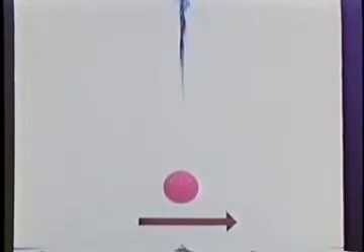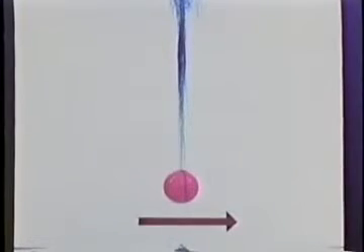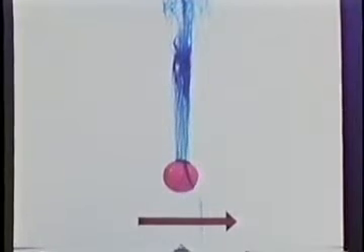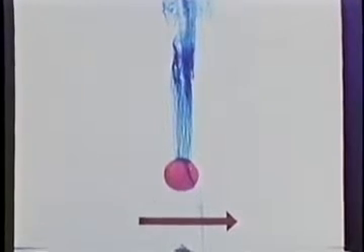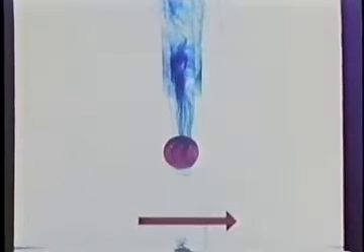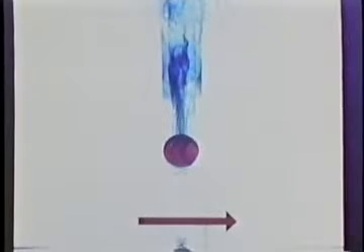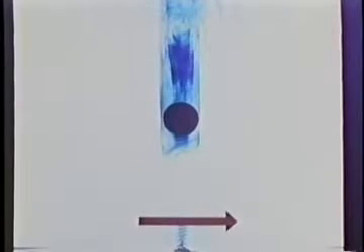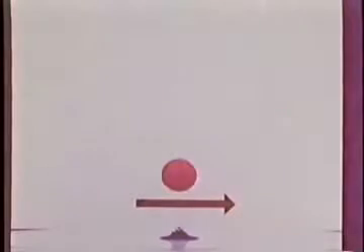Now we have changed our setup so the sphere can be towed vertically, parallel to the rotation axis. The water is in rigid body rotation. Dye crystals mark the fluid above the sphere. We start towing at a very low Rossby number of about 1%. A few minutes later, we see that the dye is largely confined to Taylor columns above and below the sphere. We will speed it up by time-lapse photography.